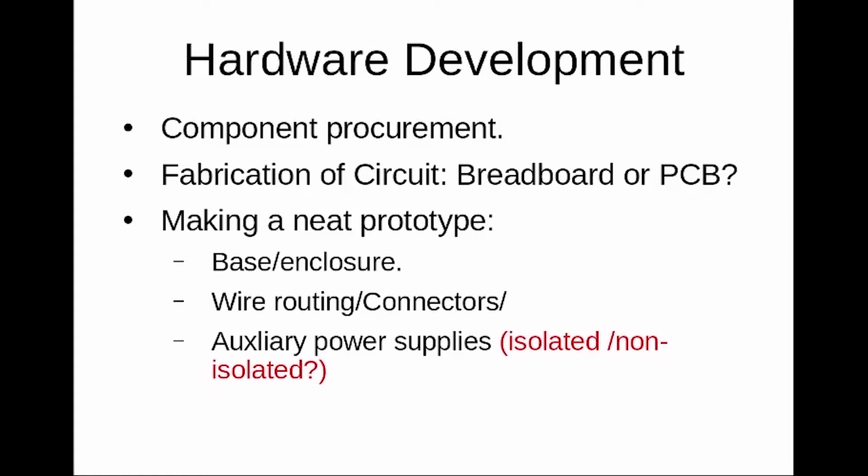In power converter projects, if the switching is higher than 10 kilohertz, it is better to go for a properly designed PCB. If the circuit is not a complicated one, you may consider even a general purpose PCB to do the job. Fabricating a circuit on a general purpose PCB is time consuming, but you can save time on the PCB design process. For practical PCB design, there are free as well as commercially available software. Depending on availability, you may opt for software like Eagle, KiCad, OrCAD Layout, Altium, etc.